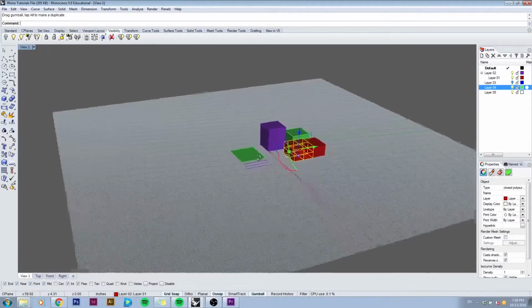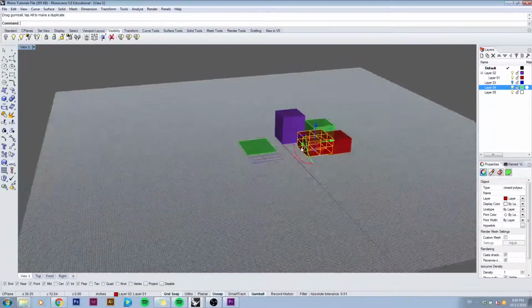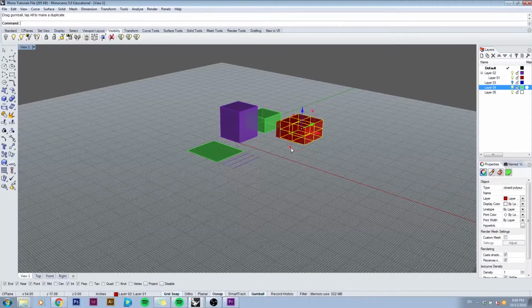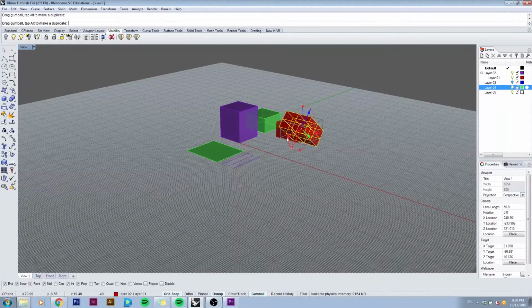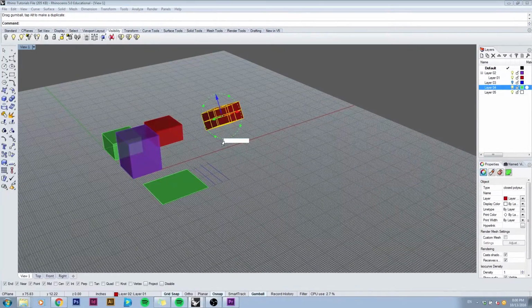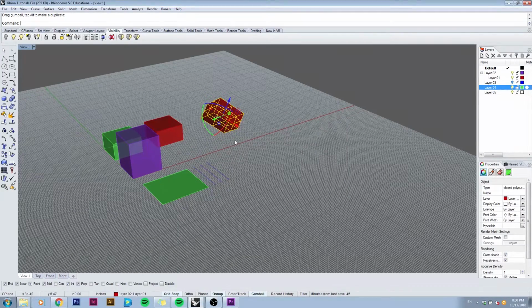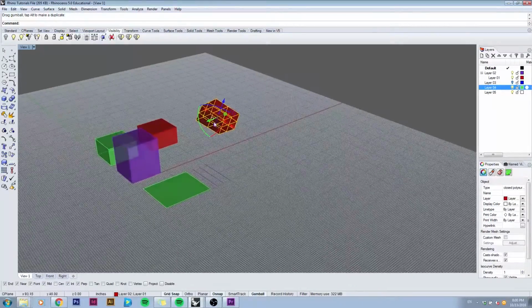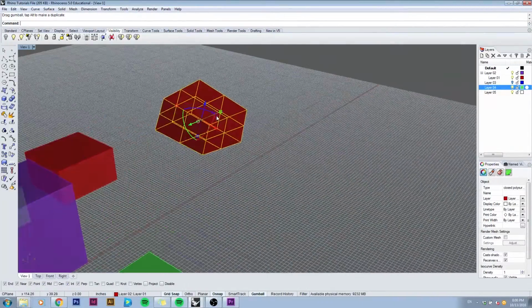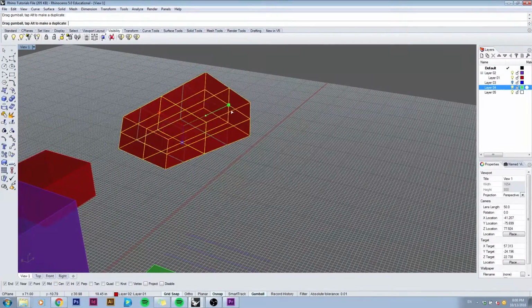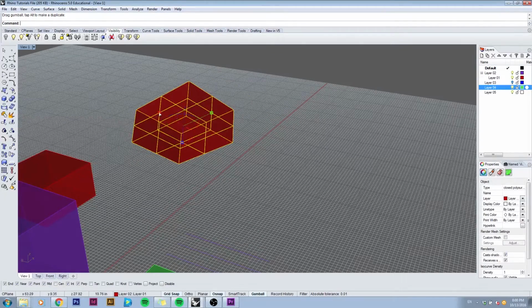The same controls apply for the arcs that you can see around the center of your gumball. If I hold and click, I can rotate the object in that plane. If I click once, I can input a numeric value in degrees, and it will rotate the object by that amount. These dotted lines with the squares at the edges are used to scale your object in that direction.